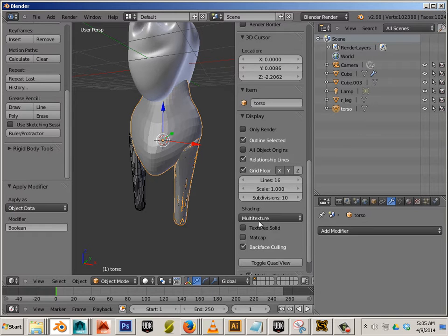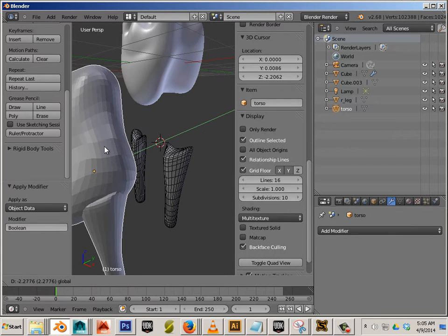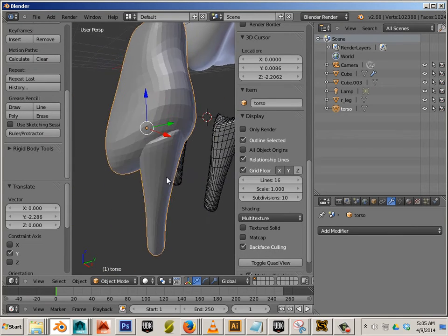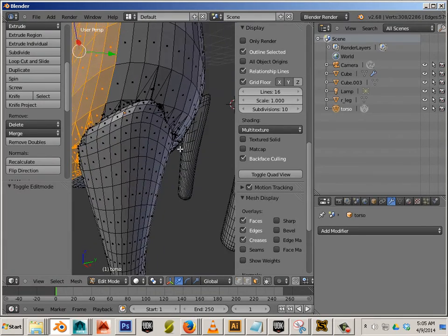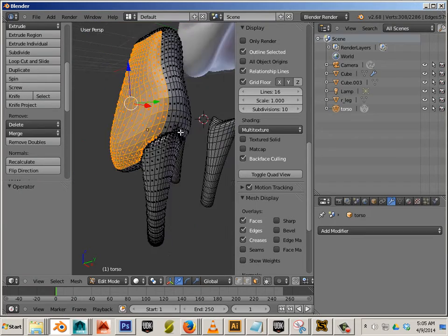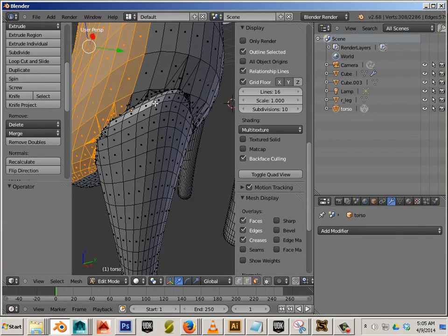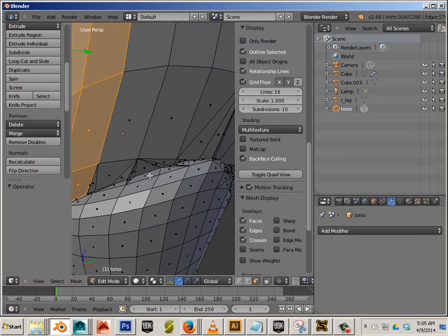And then hit apply. So what has happened is, now I have this part that's floating on top. I can move it, and you can see it's a hybrid between the two parts, and it shares its common vertices. So now I can sculpt across it. Now the bad thing about this is, you don't want to do this right away. You want to do this at the very end, because see these triangles? Those are unsculptable.